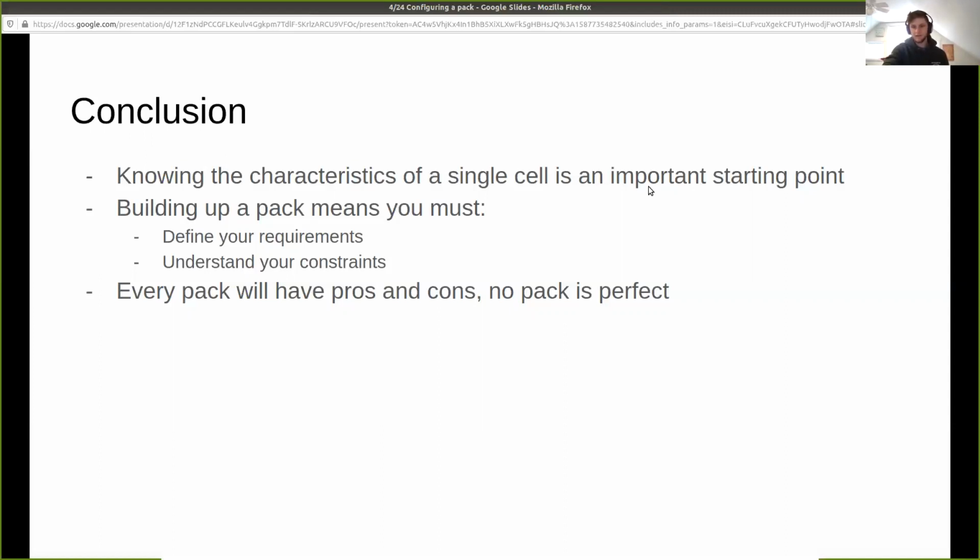Yeah, so the minimum is 2.5, and it drops off really drastically at the final percentage of the battery's life, the end of its state of charge. So we intentionally design to store extra energy so that the range that we're using the battery pack is more constant, and we don't use the battery pack in the final region of its life where the drop off of voltage is really significant. Based on our simulation, we're running it from around 4.2 volts to 2.9, as opposed to 4.2 to 2.5.